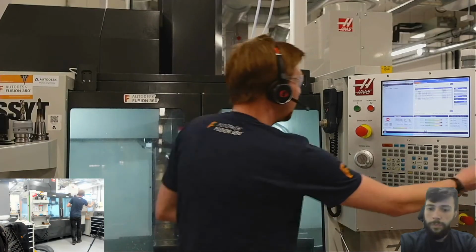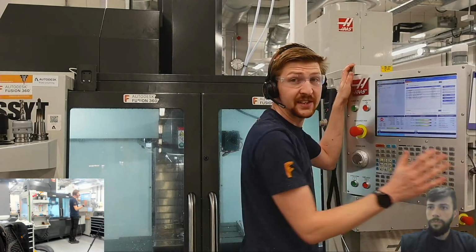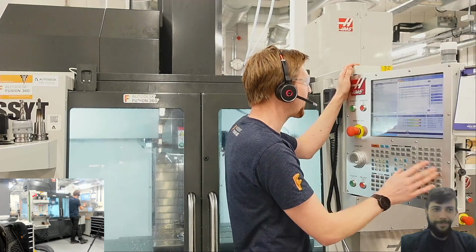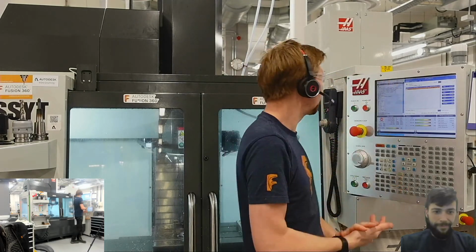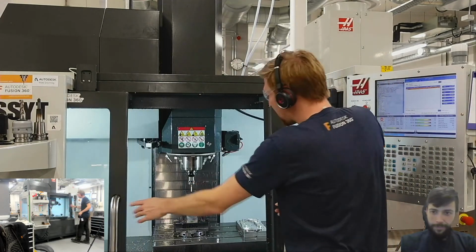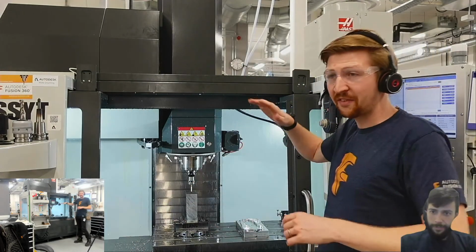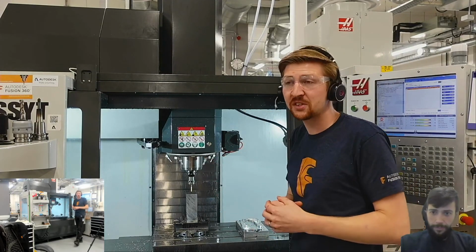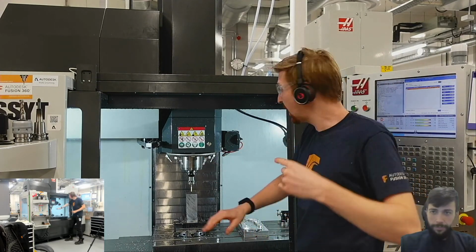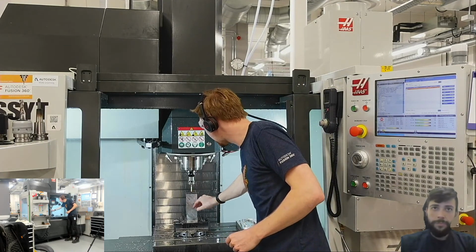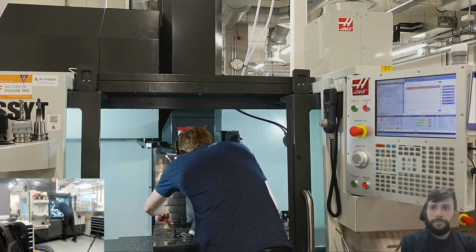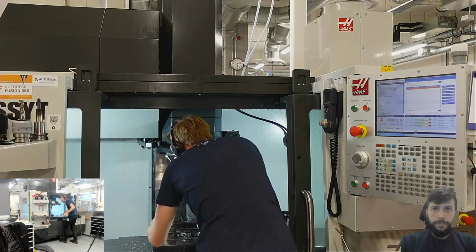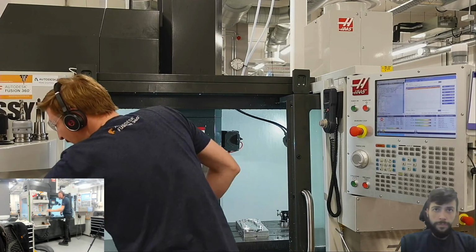So here we go. Let's see if this actually works now. I've never had that problem before. Right, brilliant. We've got our NC code now. What's going to happen is we're going to probe the top of that block. We're going to face it off, do 2 or 3 of the milling ops, and I've set it up so I can keep running it, and it's just going to keep taking 2 mil off the block every time. Then hopefully we can see that cycle counter increasing. We're going to make sure that we're happy with the cycle counter, and then we're going to go into the last thing of making a shift report.